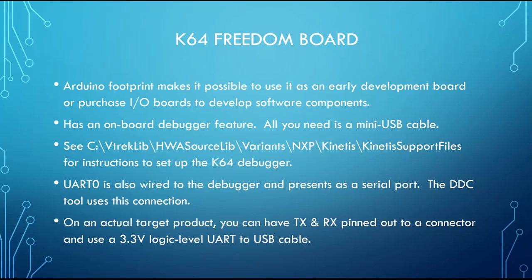Now, if you're not familiar with the K64 Freedom board, I want to go over a few things. It's an Arduino footprint, which makes it possible to use it as an early development board. You can create boards to plug into that footprint that has your I/O circuitry, or you can purchase I/O boards that use the ICs that you plan to use. It also has an onboard debugger feature, so all you need is a USB mini cable. You don't have to have an actual debugger in order to use the board.